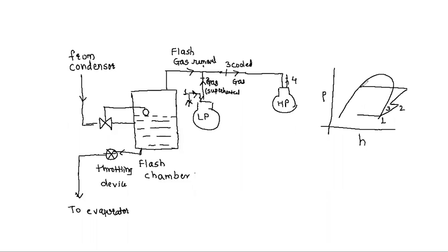Now if you look at this diagram and compare it with the earlier one, this is also flash intercooling. This is also intercooling of the refrigerant, but this intercooling is not a perfect intercooling, because in this case what is achieved is external mixing of the flash gas with the gas which is superheated. Okay, now if you want to go back and come out to this saturated curve, we need to use another intercooler which is called a water intercooler, that we would explain later. But this arrangement also is one arrangement of achieving an intercooling. So there are two arrangements of achieving intercooling.